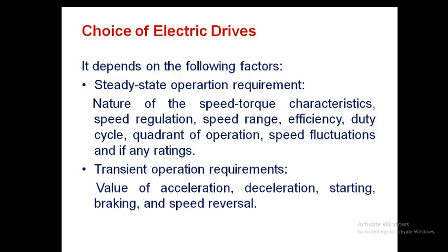So, choice of electric drives. The choice of electric drives depends on the following factors: steady state operation requirements, like the nature of the speed torque characteristics, what type of speed torque characteristics the load requires, and speed regulation, speed range, in what range we need to operate the drive, efficiency, duty cycle, quadrant of operation.